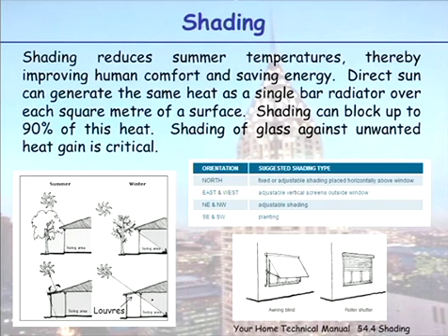On the north part of the house, because of where the sun is in the sky, you need to have horizontal shading. So an awning is enough to keep the sun out. However, on the east and west parts of your building, where the sun is rising and setting, it's important to have vertical screening. So you need shades that will cover up your window altogether.